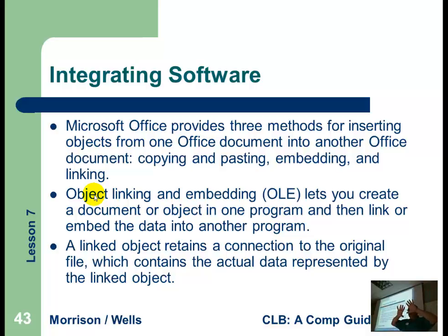Anything that's symbolic, a symbol on a drawing in AutoCAD, we can make it smart, and we can put a list of data tied to that symbol. And then all those different symbols that are related can be extracted into a spreadsheet. And that spreadsheet can be related to the drawing. And I can make a change to the drawing and the spreadsheet will change. Change the spreadsheet and the drawing will change. So they're integrated. They work back and forth.